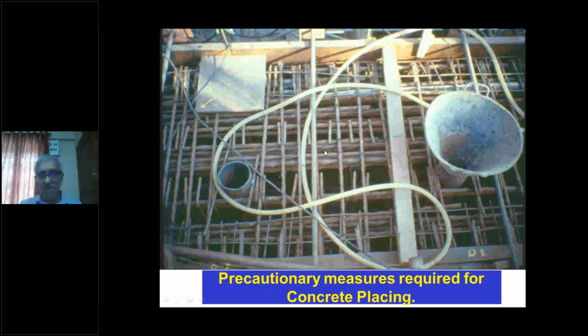You have to have pipe sleeves where you can bunch bars. You can have a funnel type of arrangement for placing concrete. All these precautions. The placer boom should go right into the lowest reinforcement so that no segregation takes place.